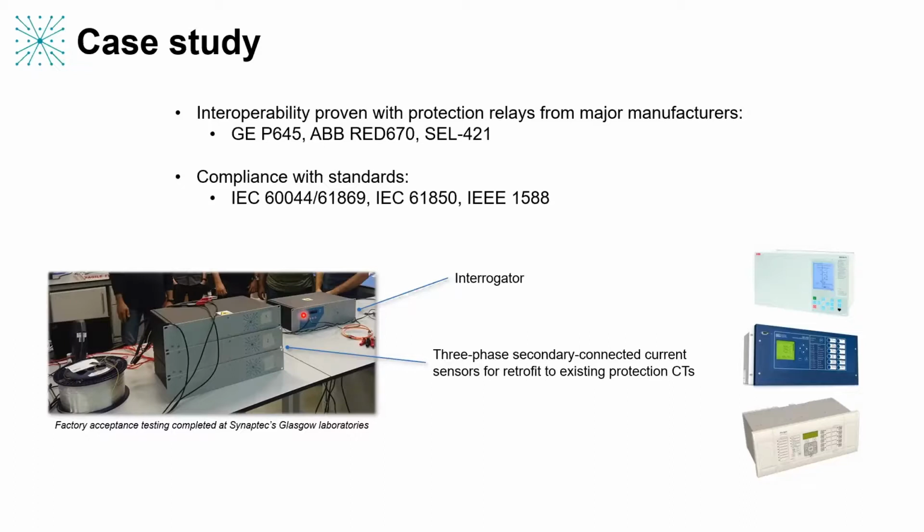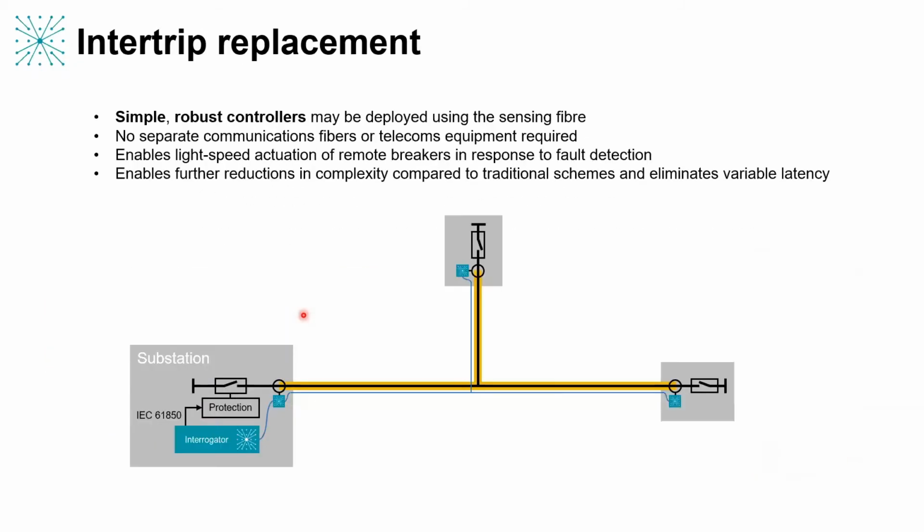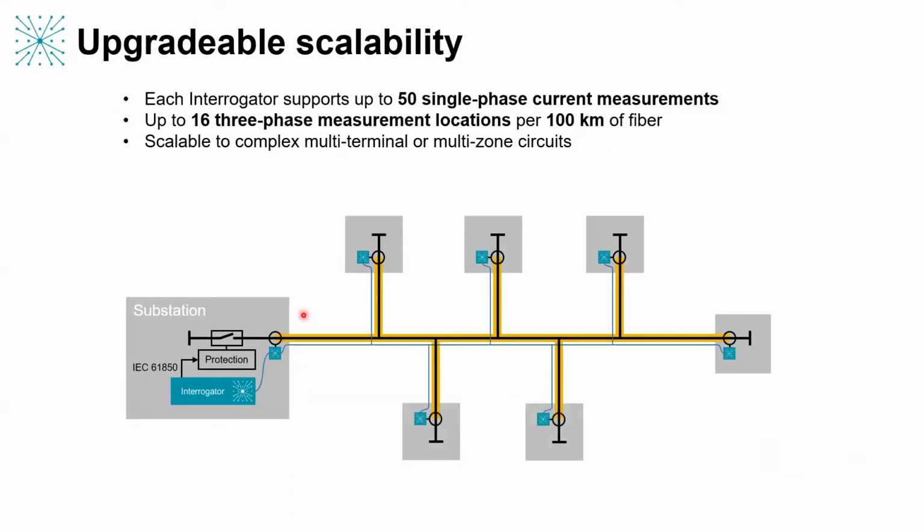So the single same interrogator can handle all the algorithms of all the other protection schemes simultaneously. Is that the right way to understand it? So that question is going back to saying, can we do trafo differential, busbar differential, REF protection all combined? Which is probably more than what you were describing, which was centralizing a simple line differential busbar protection scheme to illustrate that it's possible.